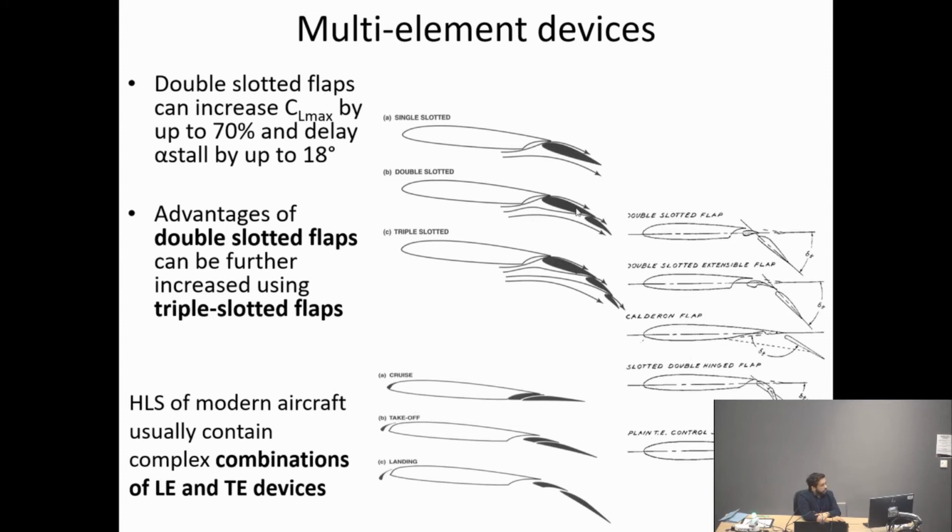So, for example, the first here, we have a trailing edge flap with a single slot. If you can see that, that's a single slotted trailing edge flap. The next design actually has two slots, and then we just call that double slotted trailing edge flap. The third one has 3 slots. Is anyone aware of 4 slots? I haven't seen it. But maybe you know, you're not telling us. No? There isn't. Anyway, so far as I know, we've only been using 3 slotted flaps like this.